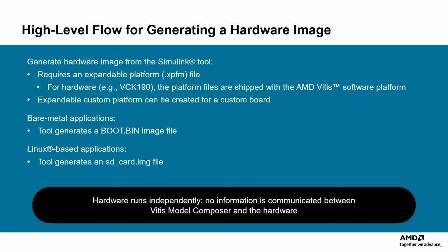As part of the creation of the hardware image, the input data samples that are fed into the design during simulation in the Simulink tool are collected. Likewise, the output data samples from the design are also collected. The input and output design data is packaged as part of the hardware image and downloaded to the hardware. The input data is fed into the design in hardware, and the output data is collected and compared with the output data from the simulation. This comparison is done by the processor and the device.